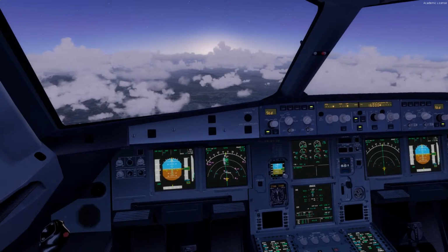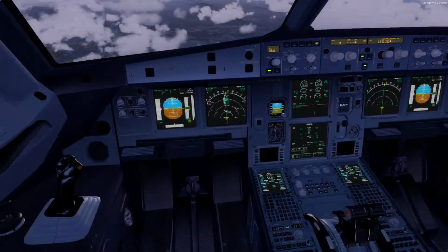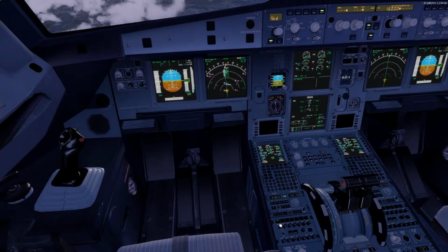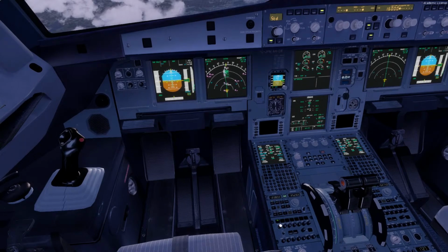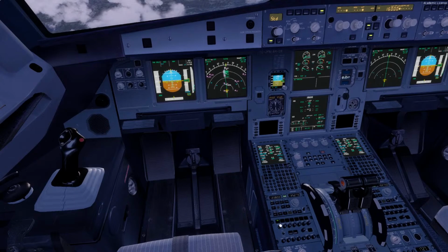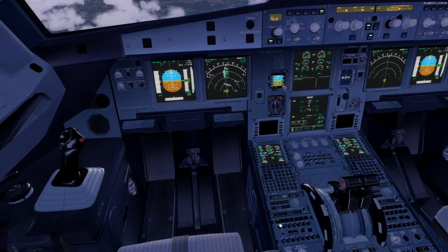We're now nearing the Slovenian airspace, and I will tune the frequency 135.275, which is the Ljubljana radar frequency. I will talk to the controller as I am now a few miles into Magam, which is the border crossing from Croatia to Slovenia, and let's see what the controller has for us.